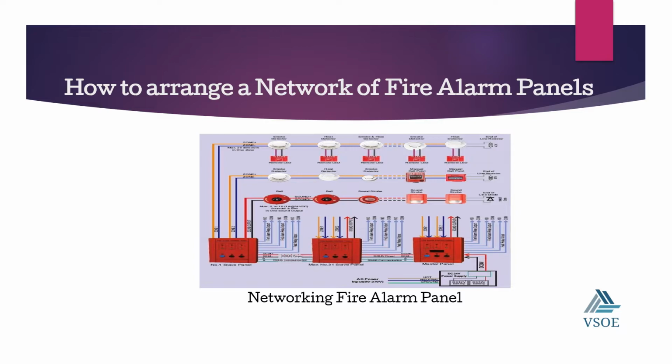By networking the panels, we can reduce certain inputs to the panel. So we're using one networking cable to actually drive the fire alarm panel.